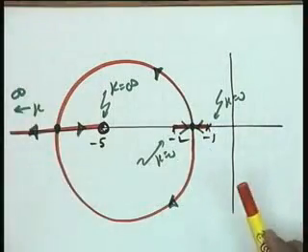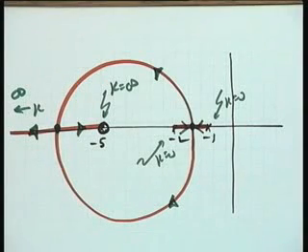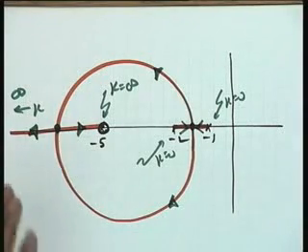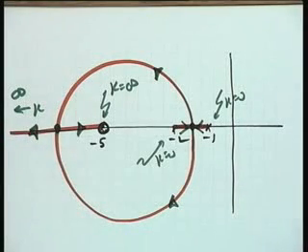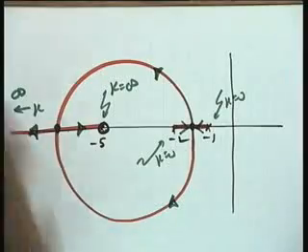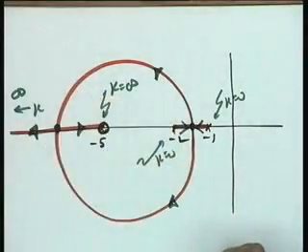But at this point you just see that if this is the root locus sketch available to you, it nicely tells you what is the effect of the parameter k on the system performance. You find that because of the 0 you have added now to the system, not only is the system stable, the system is relatively more stable because your vertical line has been pulled onto the left hand side. You see this point please.